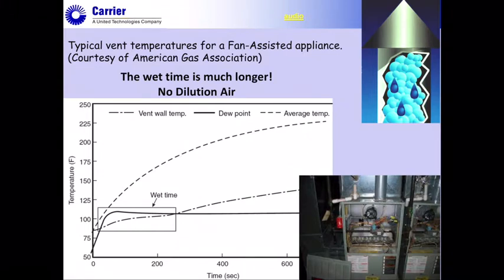Now, in this particular application, this is considered a fan-assisted appliance. I put a couple of images down in the bottom here of furnaces that are using a fan. These do not have any type of dilution air, and that's the one big thing to remember. So the wet time is actually going to go quite a bit longer.